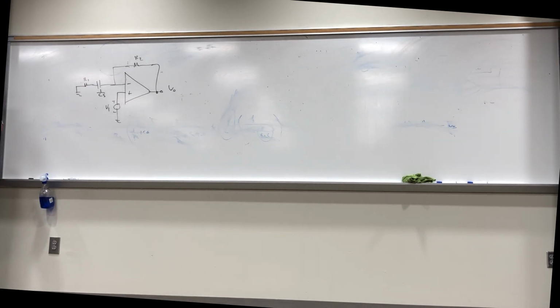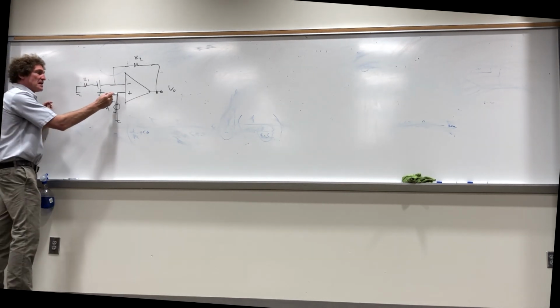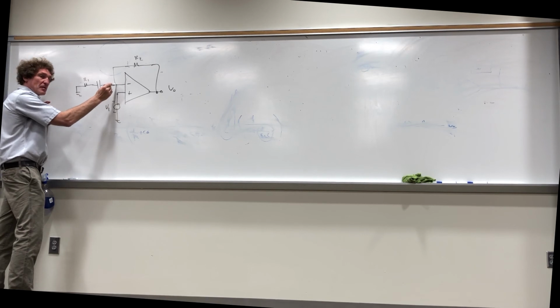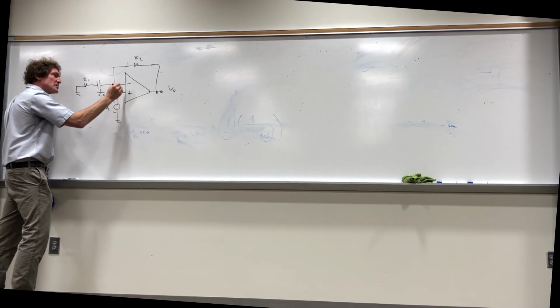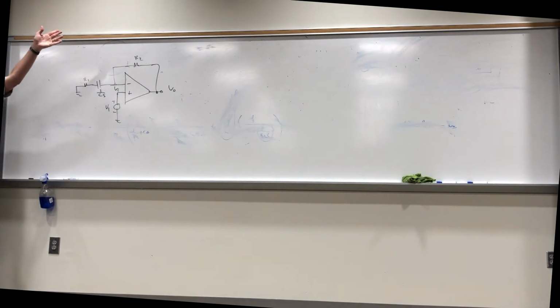Now, I know you see it now. Work with me. If this voltage is Vn or V1, what's the voltage here? V1 as well, isn't it? There's no voltage difference between those terminals. How many see that? That's the key. Once you have that, game over.